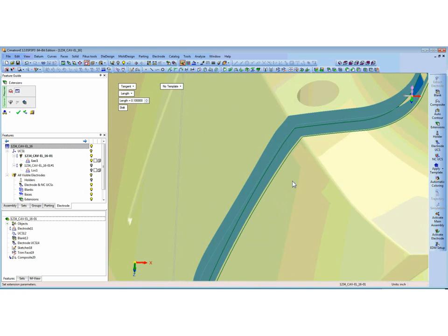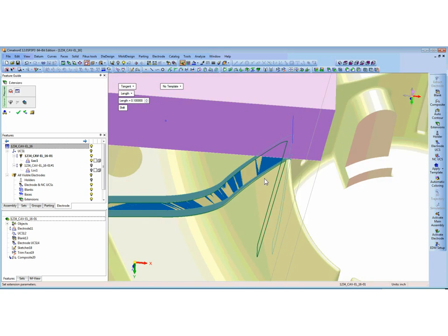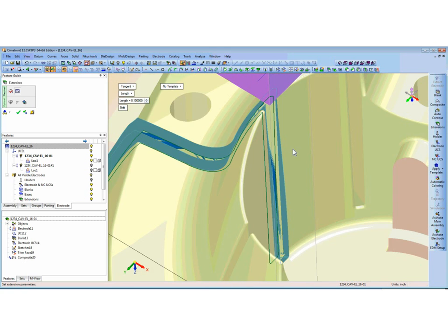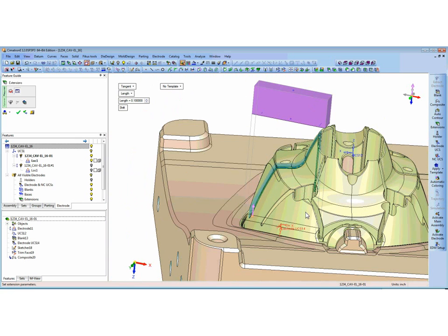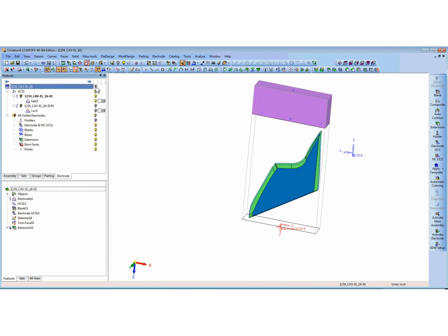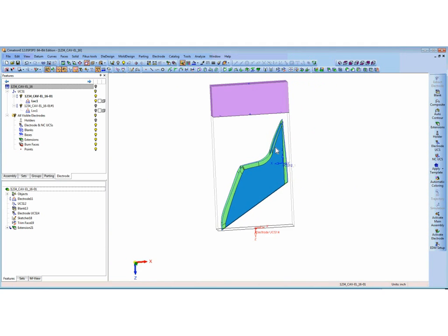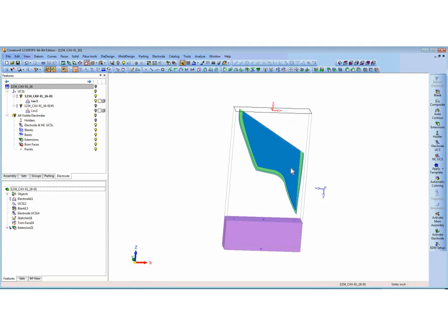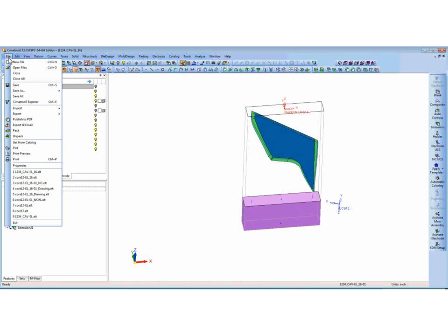We can look and see, is that giving me enough extension to get outside what I care about? It's actually burning. And that looks okay. And we could clean it up a little bit, make it better, but I'm really running out of time here, so I'm going to be a little bit sloppy and just take it right to NC. Let's save it, and let's go to NC.